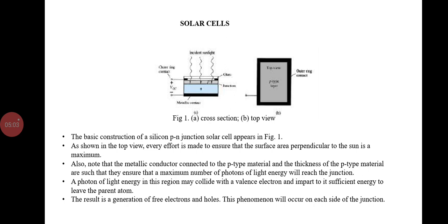As explained for the basic p-n junction with no applied bias, and also the result of an increase in the minority charge carriers, which is opposite in direction to the conventional forward current of the p-n junction. Since V equals 0 on the vertical axis, representing a short circuit connection, the current at this intersection is called the short circuit current, and it is represented by the notation ISC.